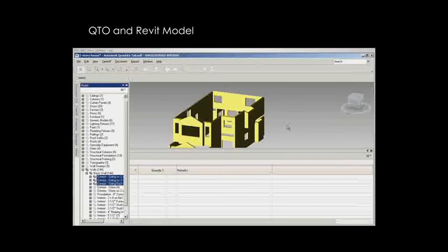And like I showed just a couple of minutes ago, one of the beauties of using BIM models is that all the takeoff that gets generated from the model can be mapped easily from the list of items. So if you know what the item is, which can be easily selected from 3D, from plan, or from a drop-down list like you see here by category, then you can just grab those and map them to the right category with a simple right click.